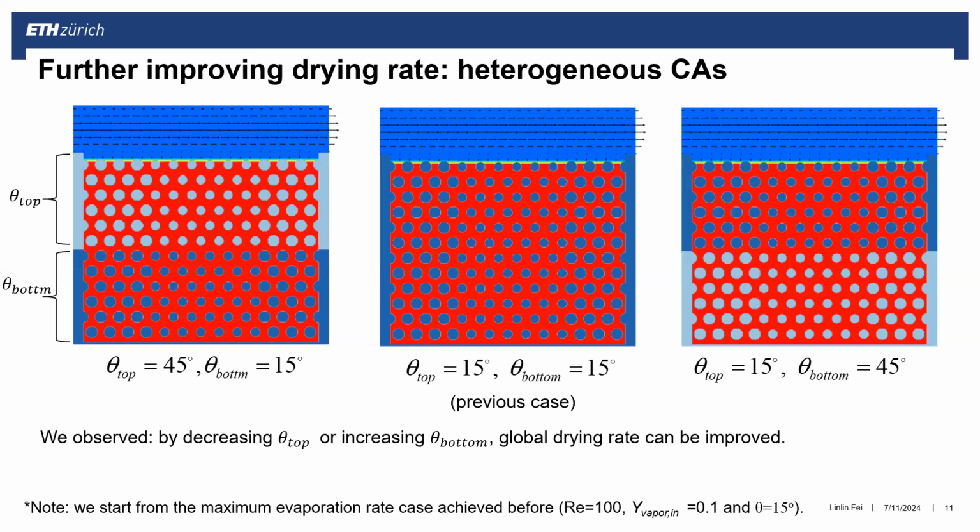Yeah, so because we want to make use of the capillary pumping effect, we want to pump the liquid from the larger pores to the small pores, so we use hydrophilic. If you use hydrophobic, actually the pumping is from the small pores to the larger pores. So the evaporation rate will be lower. I will show you, because I don't show you the movie for the bottom hydrophobic case.